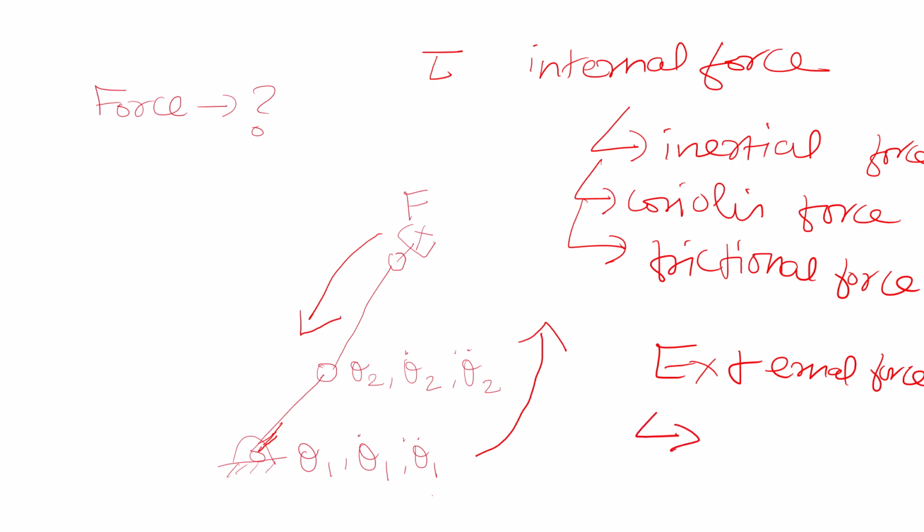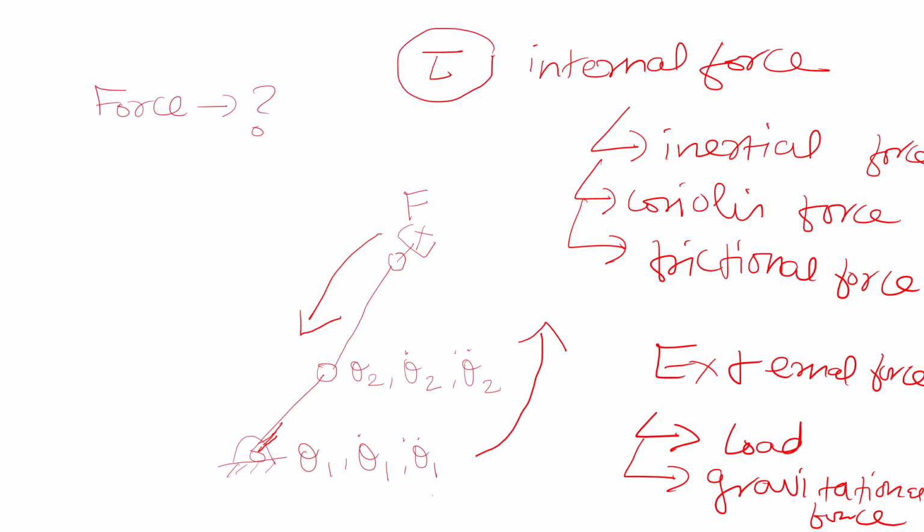These include the load and the gravitational forces. So we need to determine the various forces acting on the system when the manipulator is moving and then to find the torque acting on the joints. The torques are applied at the joints by the joint actuators.